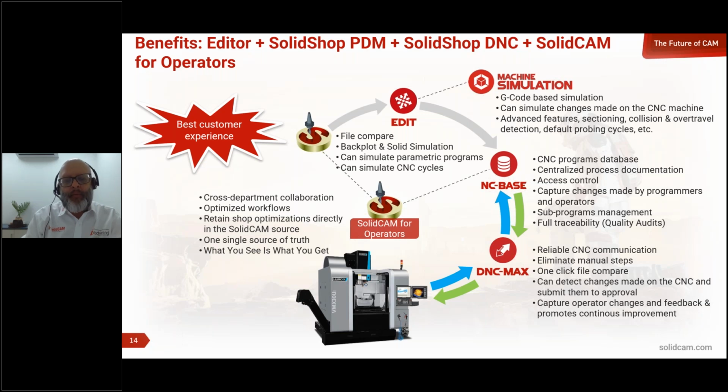Post processors can be managed by the PDM for the whole company, including the post processors that SolidCAM for operators is using. So if you make any change, for example, on your GPP file or in your VMID file, we can configure the PDM to store and centralize all post processors and track this change, control changes in the GPP. I know customers usually don't edit their files, but just to give you an idea that we can control anything we want.